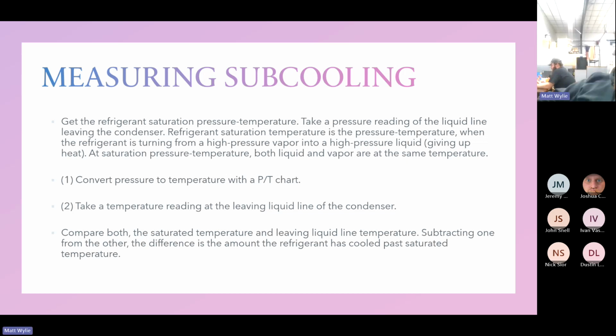They programmed it off of Bitzer's PT chart, which was slightly different than Danfoss's PT chart. If you're using your Field Piece wireless gauges, the actual PT chart they use is different. So we had to kick it old school.